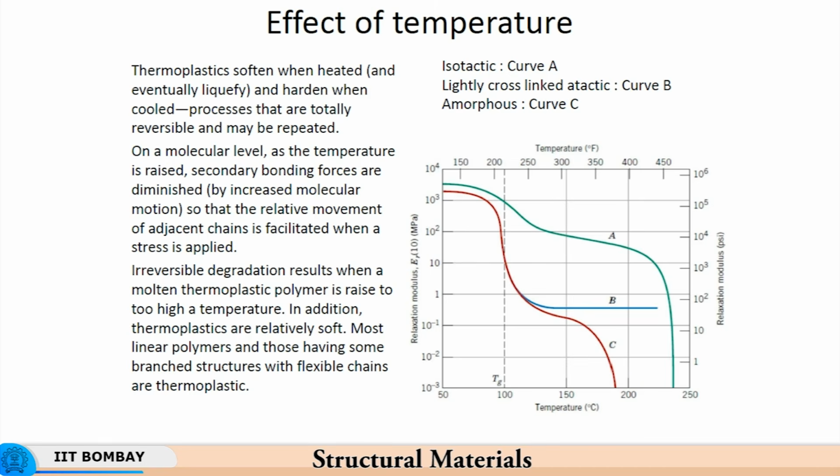That is what I had talked about yesterday when I said that if you subject the polymer to too many recycling operations, or leave it in a heated condition for a long period of time, or subject it to an excessive amount of heat, then the polymer degrades into smaller molecular units. So you may start with a polymer with a large molecular weight, which will have a lot of strength, lots of good properties, and the melting point will be very high.